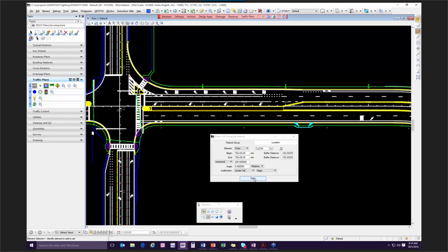And I think I may have changed my angle. We'll find out in about 2 seconds. Click draw. See how they're placed, they're facing the wrong direction? Okay, they're all right when they're over here, but over here it's wrong. So I need to flip those around. So we're going to change the angle to 180. And now they're facing the right way, but notice that this one didn't come in right.